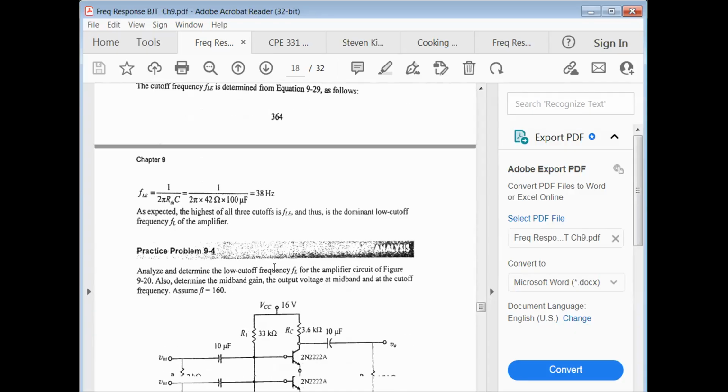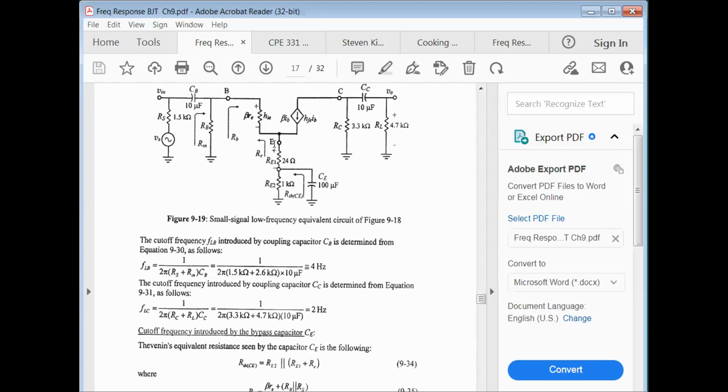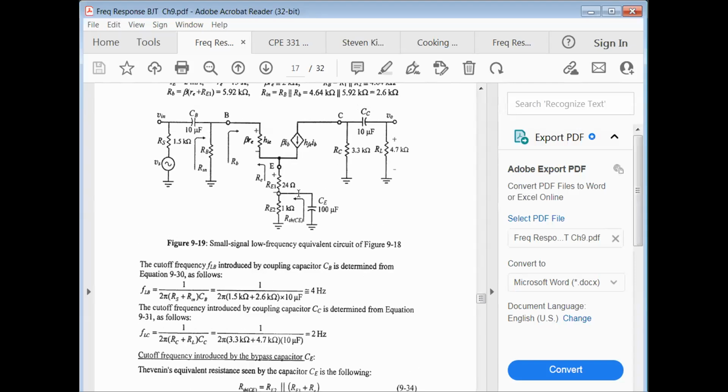What this also does, and I didn't show this to you before, this guy here also decreases your gain. So we're splitting this up, causing our low frequency pole to move lower in frequency, which increases what we call the bandwidth. So we can go lower in frequency than we did before. What we get from that also, though, is by increasing the bandwidth, we get less gain.